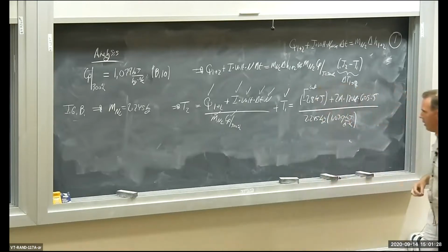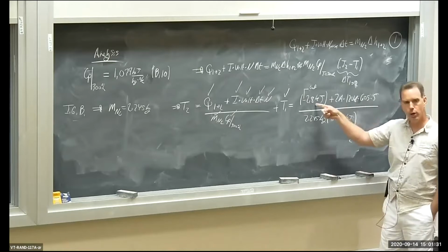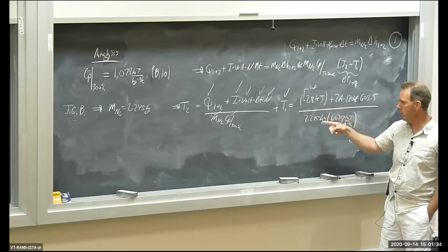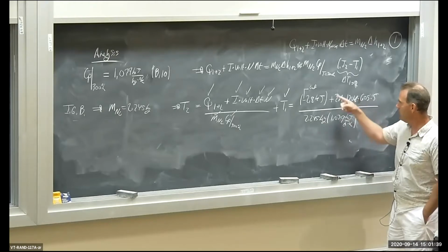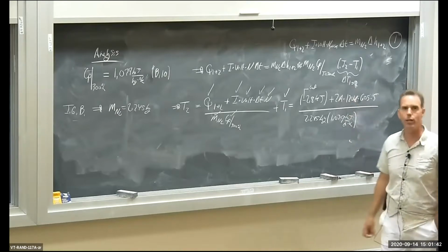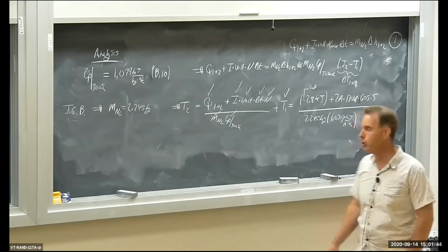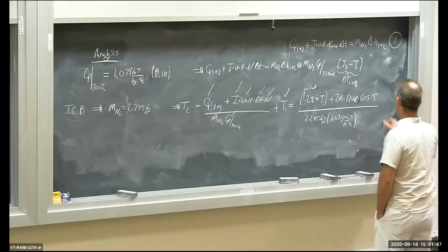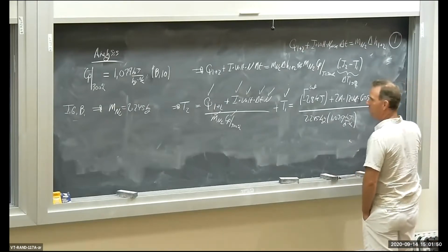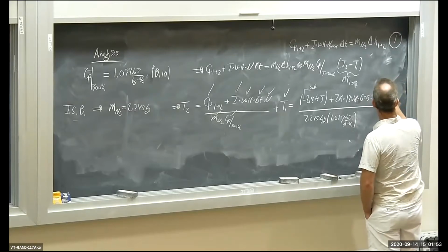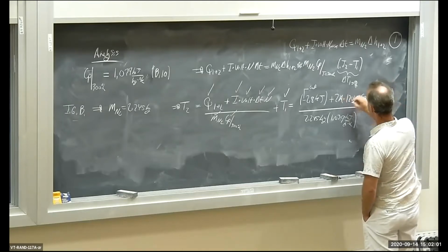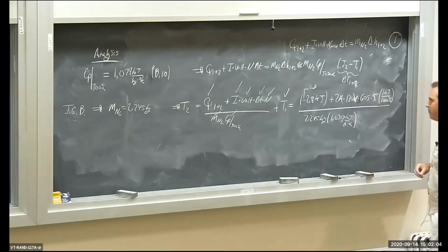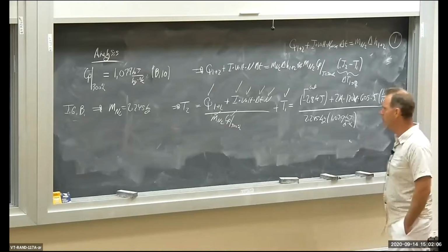Now, one little thing here. This term, the heat transfer term, has units of kilojoules. The specific heat has units of kilojoules per kilogram Kelvin. This term here, an amp times a volt, gives you a joule per second. Not a kilojoule, a joule per second. So I need to convert this term out of joules into kilojoules. So there's 1 kilojoule per 1,000 joules. And so that'll cancel out with the current, the voltage, and the seconds here, okay? And then, oh, I'm running out of room.